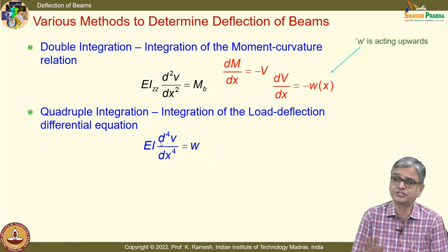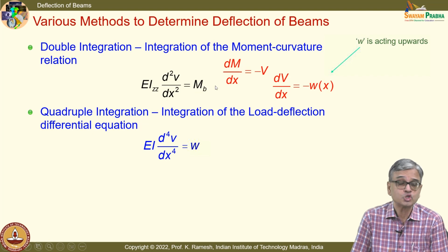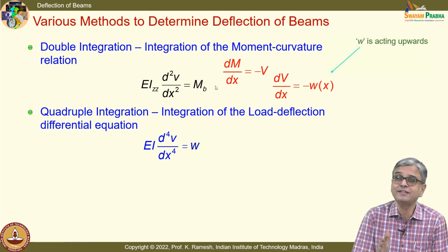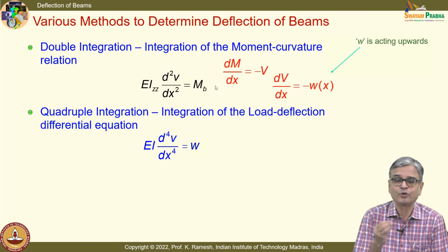It has an advantage. See, if you look at this expression, when you want to do double integration, I need to calculate the bending moment. So far, you have handled only statically determinate problems. I have also shown what are statically indeterminate problems, wherein you have to bring in what happens to the deflection. Only when you bring in the deformation, I get additional information for me to solve.